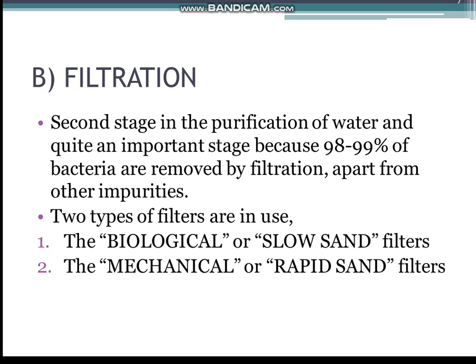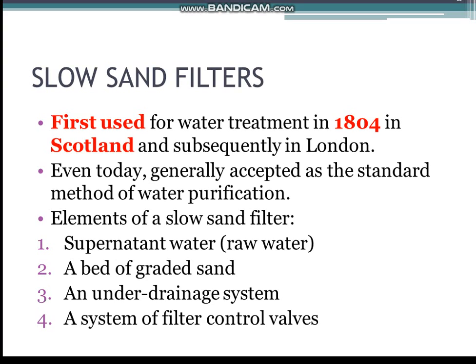Filtration. Filtration is the second stage in the purification of water and quite an important stage, because 98 to 99% of the bacteria are removed by filtration. Two types of filters are in use. The first, biological or slow sand filters, and the second, rapid or mechanical filters. A brief description of these filters is ahead.